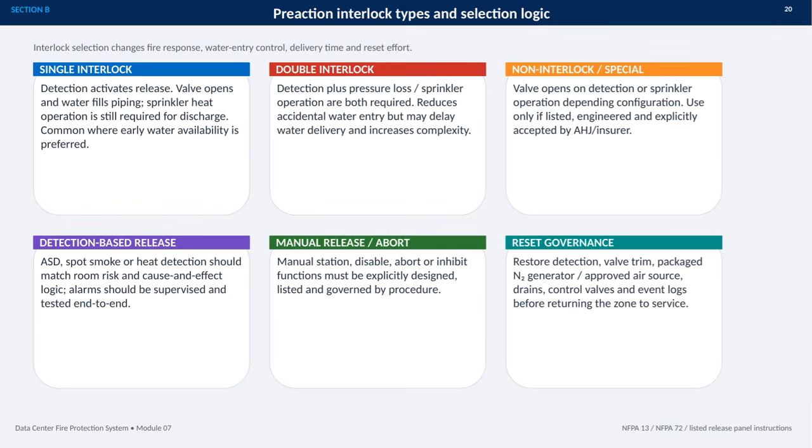Finally, reset is a governed process. Restore detection, valve trim, air or nitrogen supply, drains, controls, and event logs before returning the zone to service, following NFPA requirements and listed panel instructions.